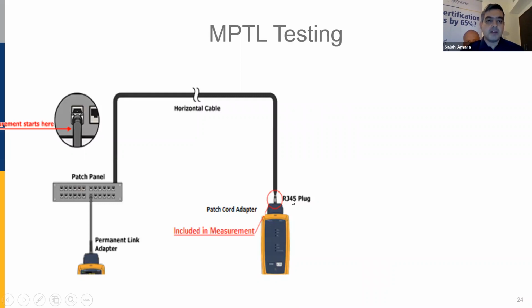So how can we test it? We cannot use two permanent links because physically we will not be able to connect it. Please always use a permanent link from one side and a patch cord adapter from the other side.